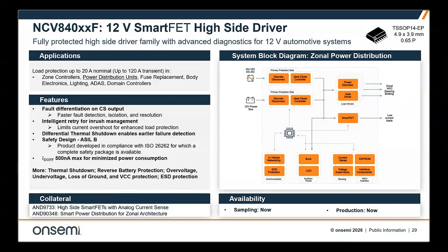The NCV84OXXF SmartFET is our 12-volt fully protected high-side driver. So a little bit more in detail here. It's a family with advanced diagnostics, providing protection up to, let's say, 20 amps nominal and up to 120 amps transient. So it targets zone controllers, power distribution units, fuse replacement, body electronics, lighting, ADAS, domain controllers, and so on.